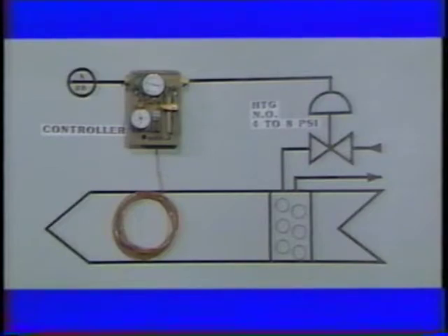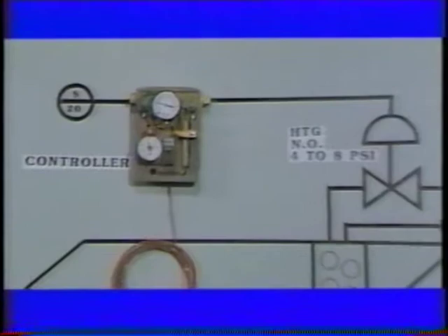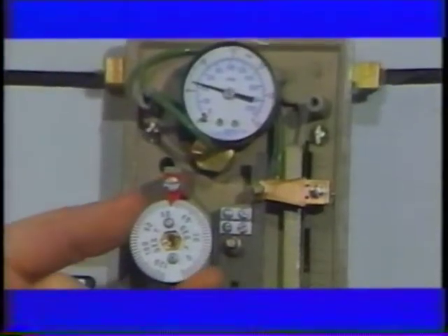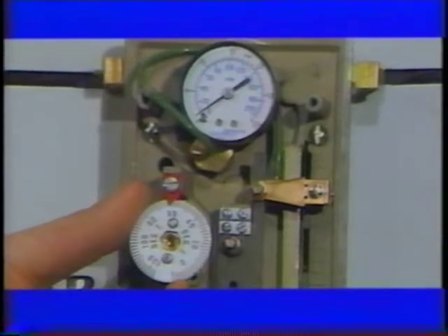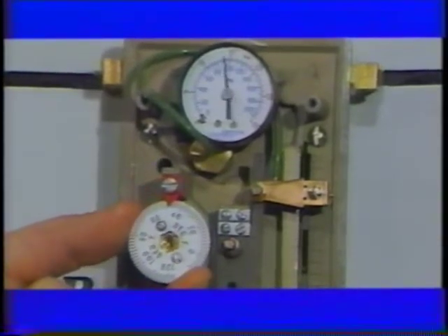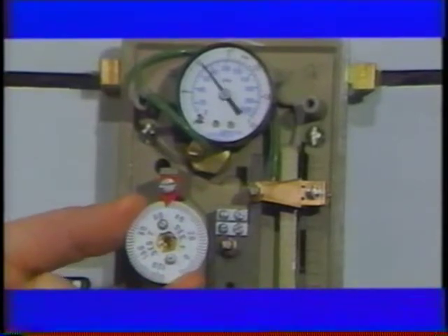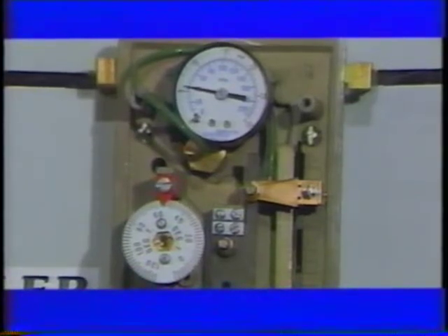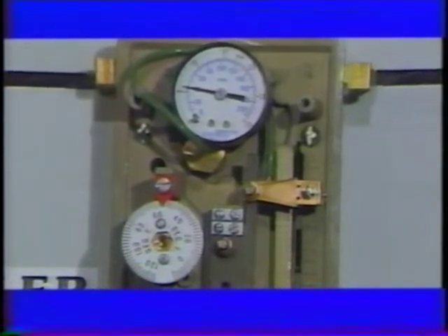The answer is no. There are three variables that can change the output pressure. First, the temperature at the element could change, causing a change in output pressure. Second, a load change could occur, which would cause the output to change, but the temperature would remain nearly constant. The third variable is that the set point of the controller could be changed, which would again cause a change in output not related to a change in measured temperature. The conclusion is that in this conventional system, there is no pressure which has a constant temperature equivalent.